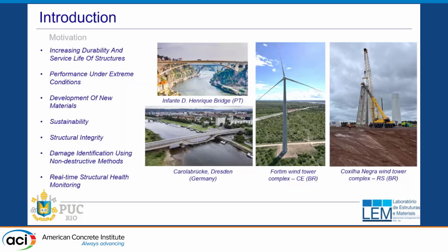Now, recently I was in Germany, and I had a chance to go for a visit of this bridge that collapsed in Dresden. The bridge collapsed at midnight without any traffic on it, and the problem was attributed to, not stray current corrosion, but primarily just the fact that it was built in the early 70s in East Germany. It was post-tensioned, and there was absolutely no way to tell from the surface of the bridge that there was corrosion. So this is the corrosion of the pre-stressing tendon.